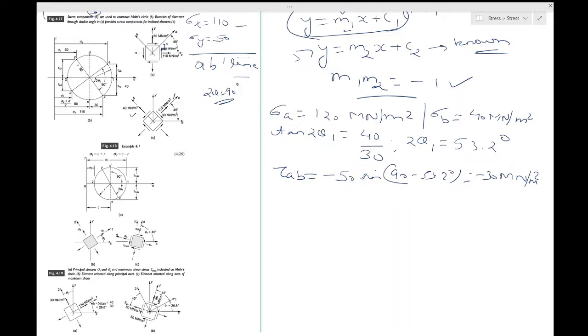Let me give you one example of a solid. Think of this as one of your solids, maybe like wood from the bark of a tree. This is how you can do a compression test, or a tension test in the opposite direction. You just push it, and then you measure the forces which you are applying, and then you can get on with doing some sort of mechanical analysis.